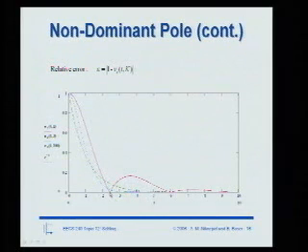why can't we just stop here, right? Why can't we design a system that settles at, let's say, 2.3 time constants, and we have really good precision? What's wrong with that idea? Why wait 7 or 8 time constants to get really high precision? You can just stop. Make your system basically 45-degree phase margin, and then just design your system to stop after just about 2 and some time constants.